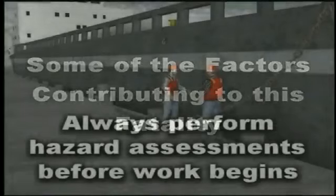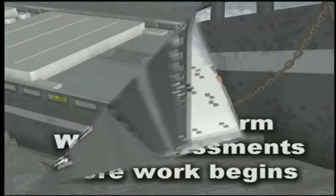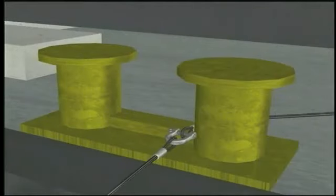Let's look at some of the contributing factors that led to this fatality. A hazard assessment was not performed before the work began. Riggers were not properly trained to perform the tasks they were assigned. The sling assembly used was not properly sized for this hoisting operation. For this job, only slings that fit through the bit should have been used.